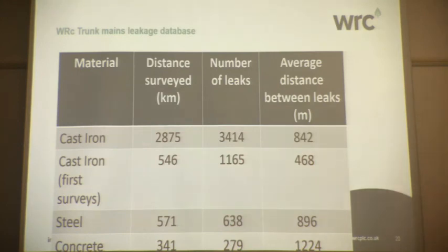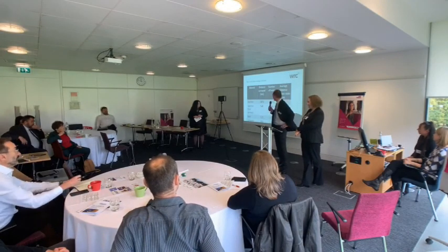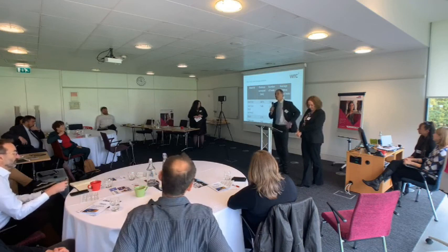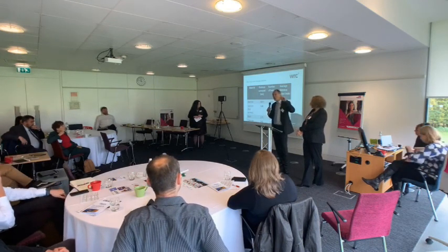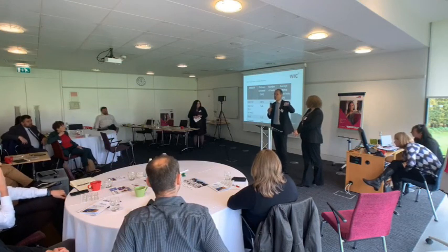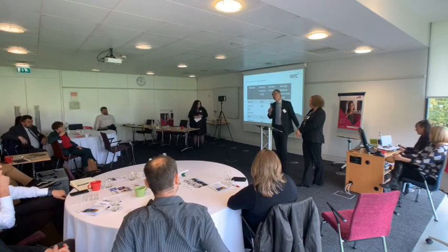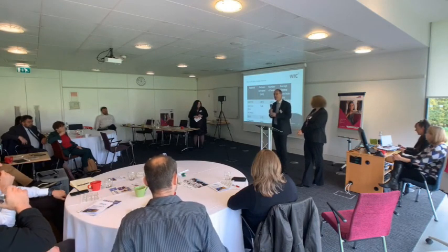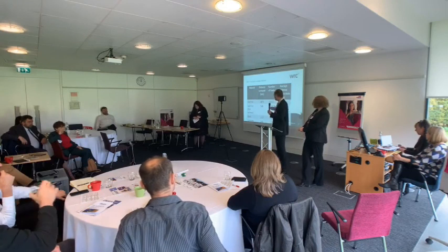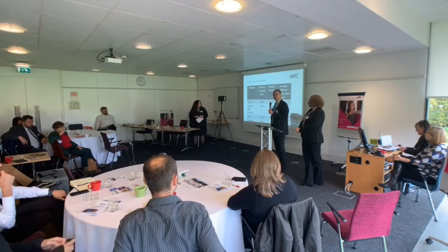No, I'm not sure that that's necessarily the case. What you'll notice is there's no ductile iron showing. I think it maybe was on the bottom, but clearly ductile iron would show up as well. It actually shows up quite poorly because the ductile iron inspections we've done have been specifically to find a leak that's known about on a pressure test of a new pipeline very often, rather than just random leakage detection. So ductile iron would look poor, but actually its performance generally would be better.